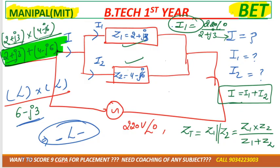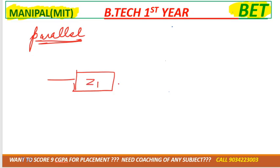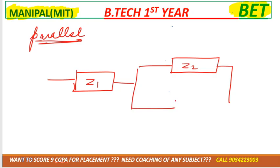So see, this is one of the methods by which we can get I. Another method is we can separately calculate I1, that is V by Z1, or we can get I2, that is V by Z2, then we can add them. Okay? Now the question arises: whenever you use a parallel circuit, it's better to use the current division rule. And we need to use the current division rule when you get this kind of circuit, as I just told you. This is the exact question you got in the 2024 paper, that is, the end term paper.